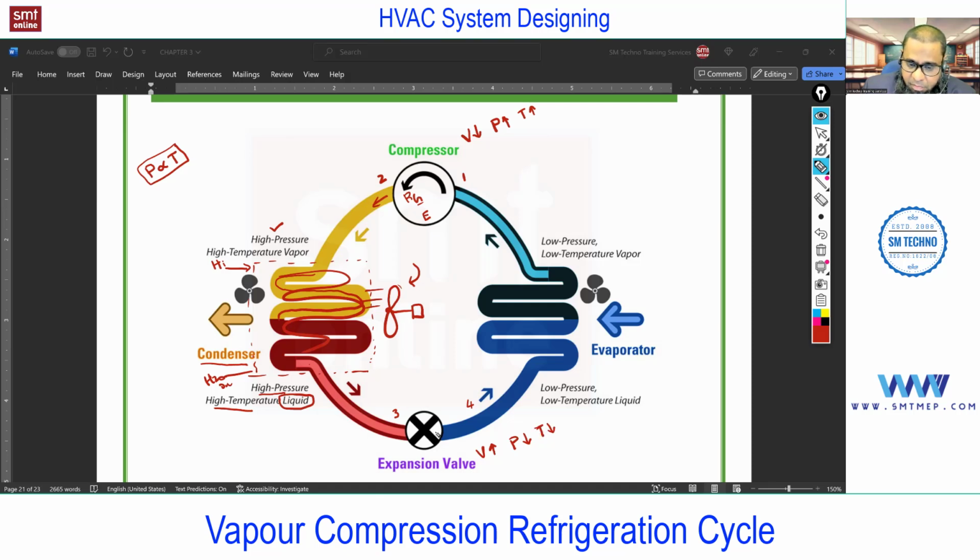And you see, when the refrigerant comes out at low pressure after the expansion process, the pressure is so low that some amount of refrigerant flashes and changes to vapor by extracting heat from the remaining liquid refrigerant. We know that as the pressure decreases, the boiling point of the substance also decreases. So at the outlet of the expansion device, some amount of refrigerant will flash and extract heat from the remaining liquid refrigerant, further cooling it down.